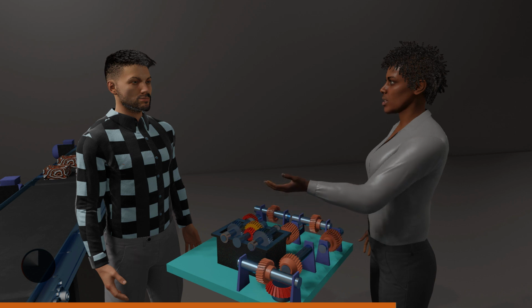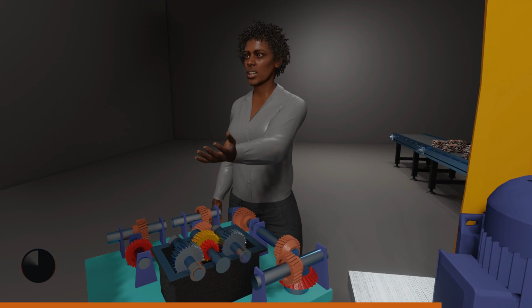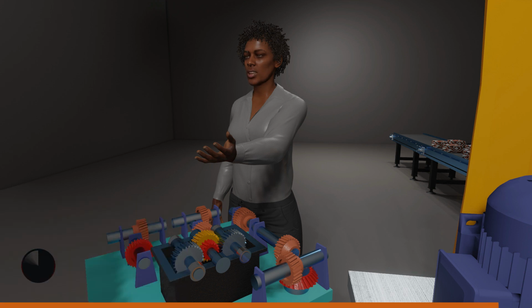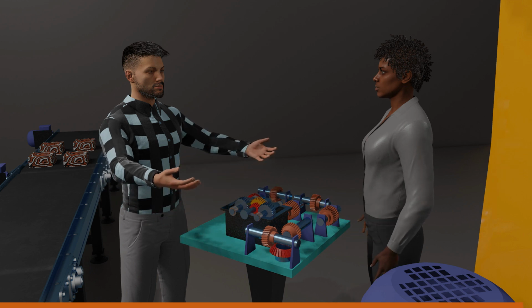Helical gears offer high load capacity, which means they can transmit high amounts of torque and power without failing. This makes them suitable for use in applications where high loads are present. Finally, helical gears are more efficient than other gears. This is because the inclined teeth allow for a more gradual transfer of power from one gear to the other. This reduces the amount of power lost as heat and increases the system's overall efficiency.